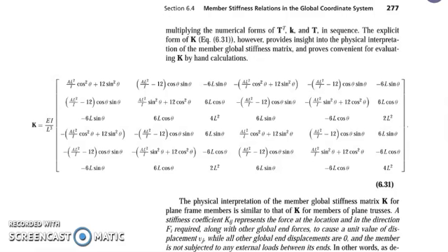And to continue, our capital letter K, that is our stiffness coefficient in the global coordinate system, is equivalent to this equation. So still, we have the presence of cosine and sine theta and our area and the length for every member. So this is per member. So you have to compute. If we're going to make use of the stiffness coefficient in the global coordinate system denoted by capital letter K, so this is being computed per member.